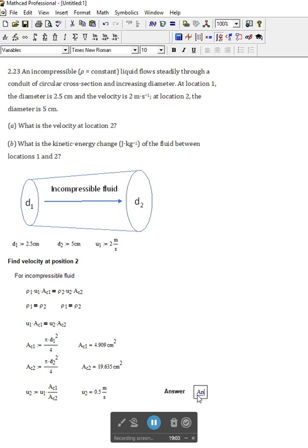And note, you can type in text. Right now, MathCad thinks this is a mathematical variable. But as soon as I hit the space key, MathCad realizes that this is now text. And so everything that I type in after this will be text. If I want to delete something, I can select it and hit delete, or I can select the box and hit Control D, and I delete it.